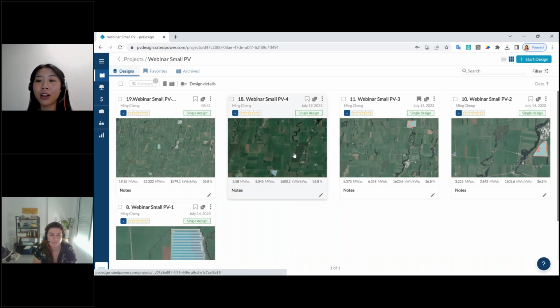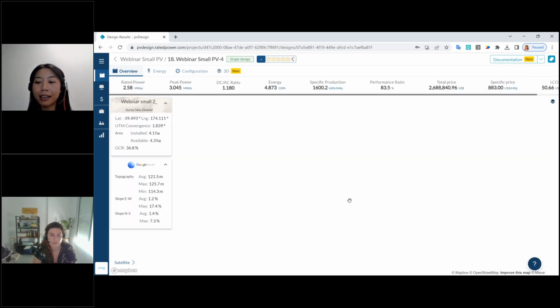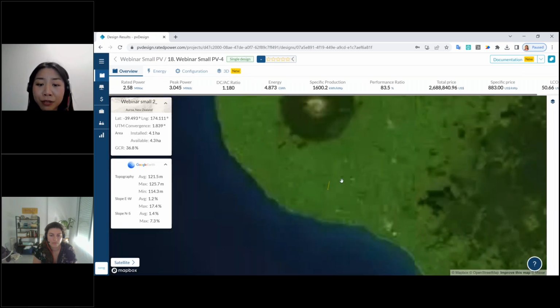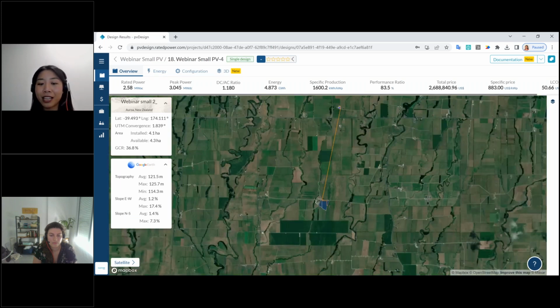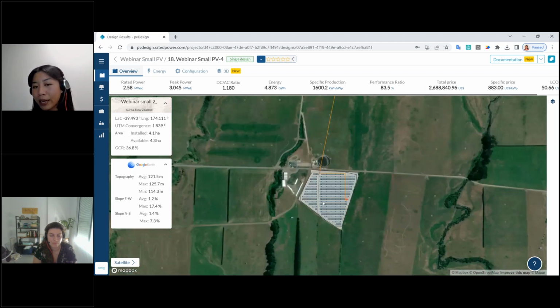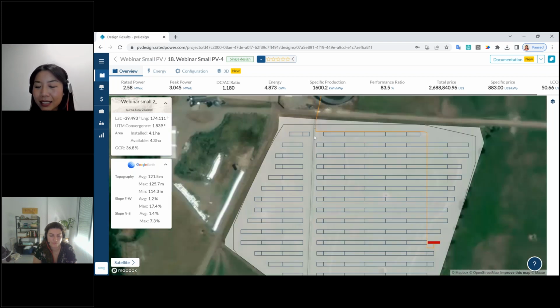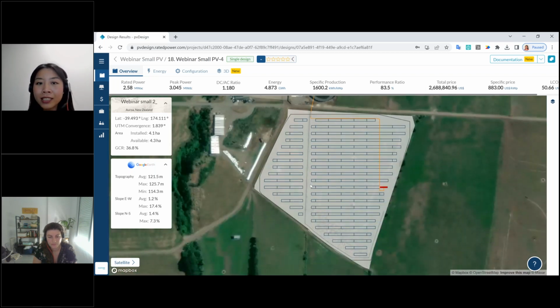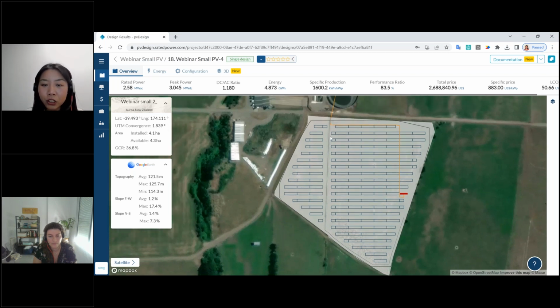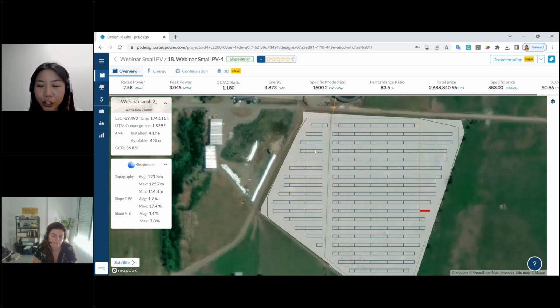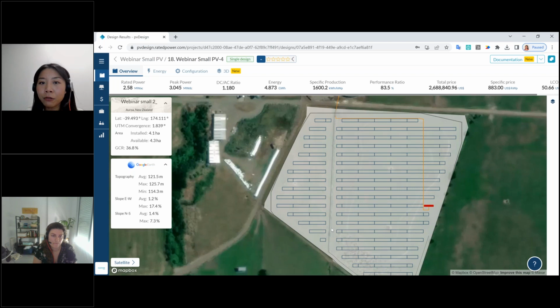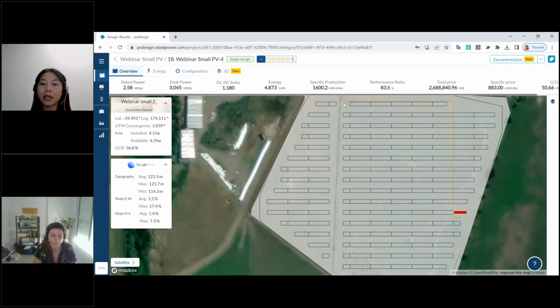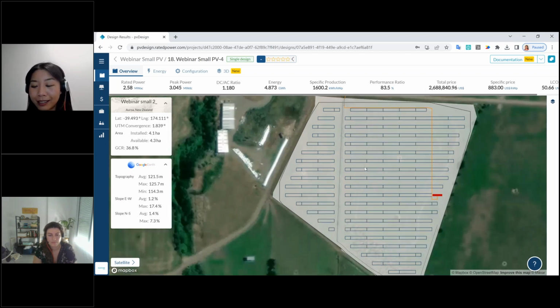And the fourth one would be a land in the south of the range that I was considering. This land is actually quite simple. However, it does include a public road that's crossing the land itself. So in this case, I have enabled the shortcuts function in pvDesign, and I've simply drawn a line feature across it. And now you can see that the software is considering the pre-existing public road as my internal road in the future in the land site.